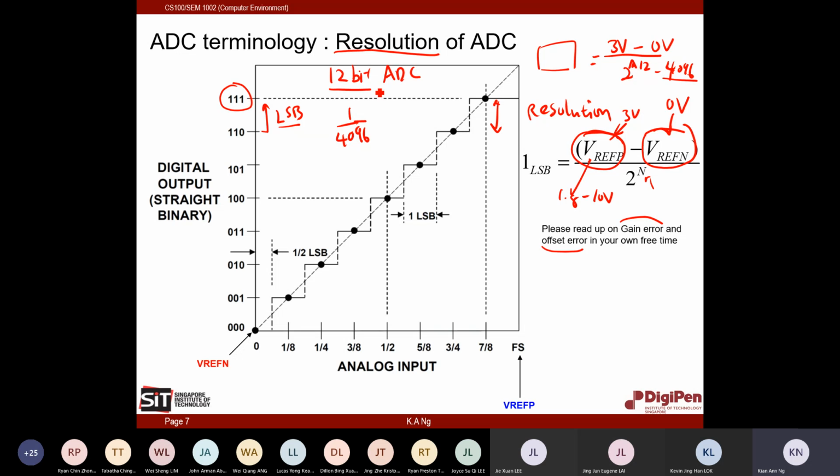So in a way, the 12-bit ADC may actually behave like an 11.5-bit or 10.5-bit ADC, which means the resolution is actually less. Depending on how good their marketing department is, they may hide this fact from you. So please take note. When you're doing really high precision work, you have to take note of this. I know some of you here do audio, so I'd like to share this with you.